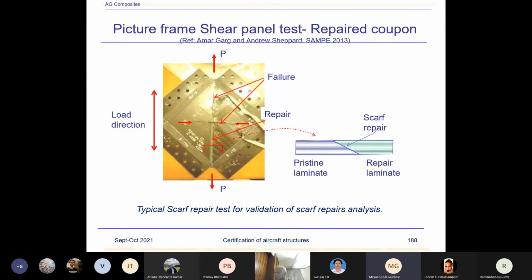Yes, sir. This was interesting actually, particularly the calculation or the measurement of the factors which we consider while arriving at allowables. That was particularly very useful for us. Yeah, if you are interested in reading about it, Mil Handbook 17, Volume 1. So these knockdown factors, what we should apply to the B basis values mostly we use.